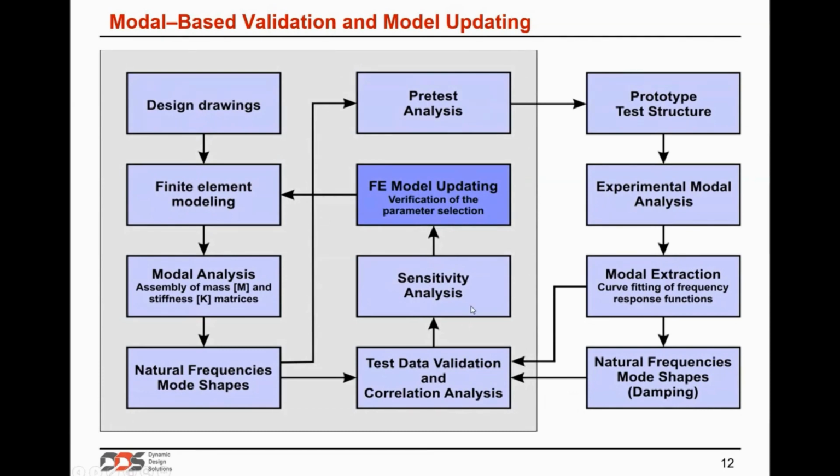It's also good practice to use the baseline finite element model to do a design of the test setup. So we call that pre-test analysis, which is about the optimal choice of the sensor locations. If it's for the mechanical industry, there's also a choice of how to excite a structure with hammer or shaker, and how to suspend the structure if it's a lightweight structure.